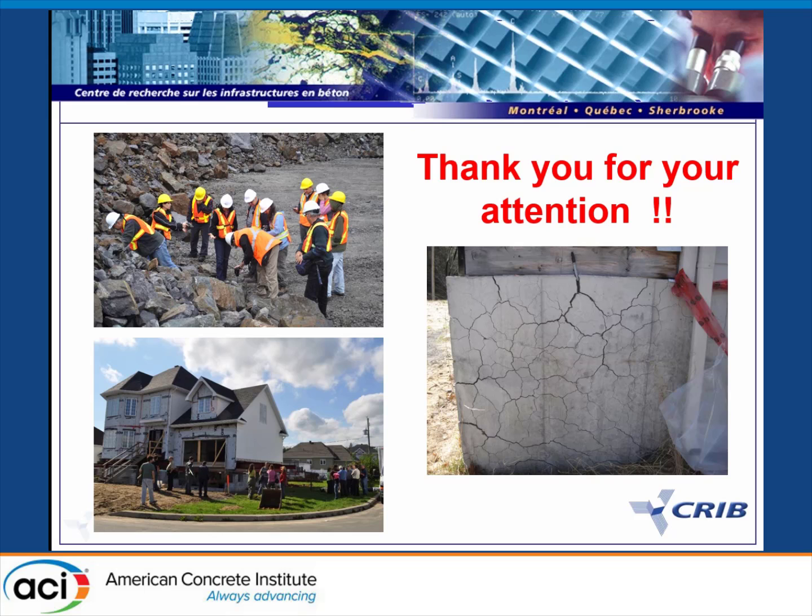If you have aluminate, and high sulfate content, then you also have the ettringite. But the thing here is you don't need aluminate for the formation of the thaumasite, and that's the bad thing. And if you have a limestone filler concrete, you will have more carbonate present in your system. Then if you have sulfate from the oxidation of the sulfide with high humidity, that can be a huge problem.